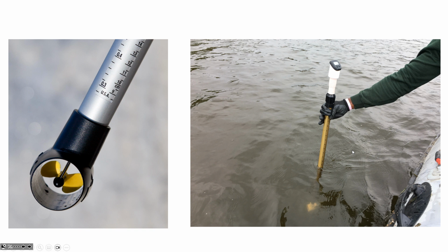Now, on the subject of velocity, one way that we can make physical measurements of velocity in a channel is with devices that you dip down into the water, and you can see that this looks like a propeller. Really what it's doing though, it's not moving the water, but it's being moved by the water. And so this device would have sort of a calibrated understanding between how many RPMs this little impeller is doing, and then on the digital scale it would tell you either how many meters per second or how many feet per second. And you can notice that there are markings on the side so that they could measure at certain depths and know what's the velocity profile.